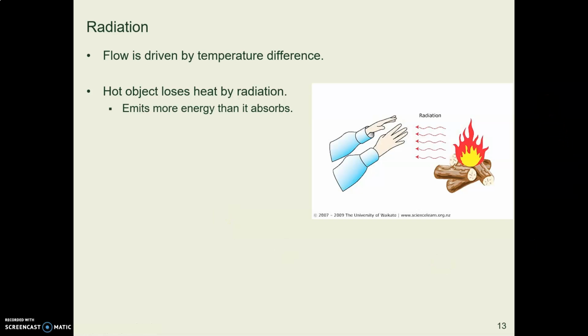What is interesting about this for an HVAC technician is that you can have a device that emits heat through radiation, like a wood stove or an electric space heater, and you can feel comfortable even though the air in that room might be cold. The air does not have to be the same temperature as the heater. So a device that emits radiation is actually economical, efficient.